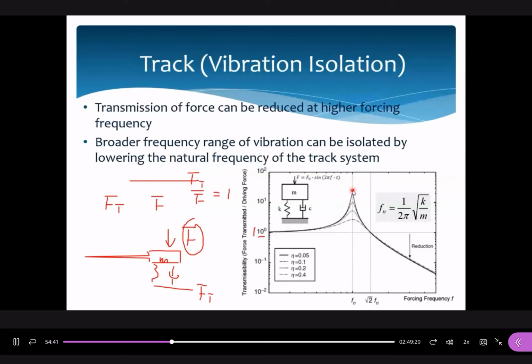We are talking about the impact force, okay? When a train is running on the rails, impact force could be generated. Why we call this P2 force is because we still have P1 force. P1 force is at high frequency, so we don't care about this one, and its operation time is shorter than that of P2 force. P2 force is under low frequency, 30 to 100 hertz. So that's why we care about this one, because the major structural-borne vibration effects come from P2 resonance effects, okay? For this one, let us go to how to calculate the natural frequency in the next lesson.